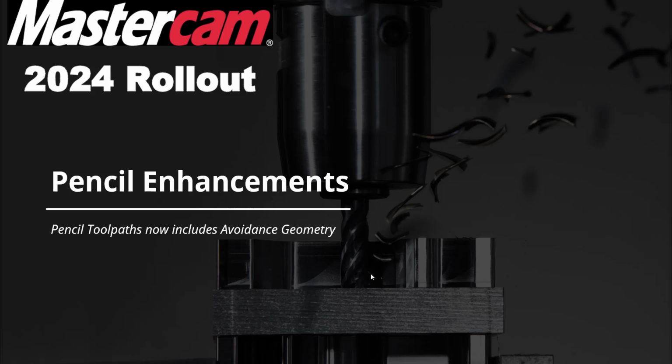I love the pencil toolpath. I still remember when it came out. I believe it came out in version 9. It was in a mold shop, and it made a big difference. What it does, you can pick the whole part, and it just traces where the cutter hits tangent to 2 walls at once, or 2 spots at once. So it basically traces all the corners.